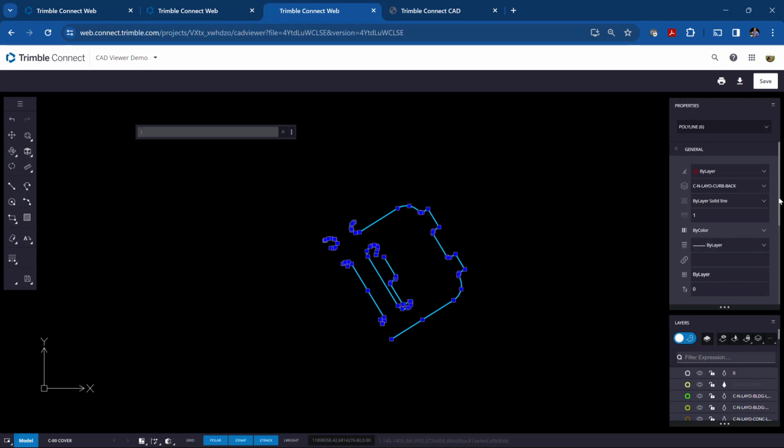So if we pick all the polylines and we scroll down, we can set the geometry. You can see that it varies on some of these. So it doesn't look like that's the thickness. This is the Z. So it says varies on that. So let's change that to 0. All right. So now they're all flattened.